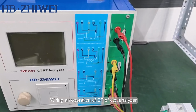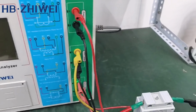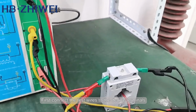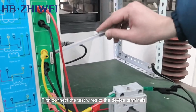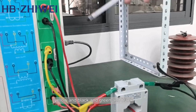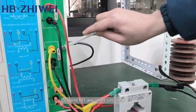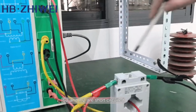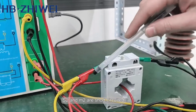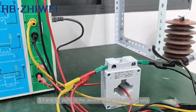Wiring and operation of CT-PT analyzer. First, connect the test wires to the device terminals according to the colors of red and black, yellow and black, and green and black. S1 and M1 are short-circuited, S2 and M2 are short-circuited, and they are inserted into the S1 and S2 ports of the device under test respectively.